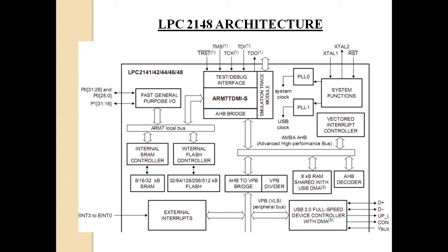Otherwise, if some sunlight is allowed to fall on that, sunlight also will have a certain amount of UV rays in it. So those UV rays may corrupt the data present inside the EPROM. In order to avoid that corruption, one sticker will be pasted. So that IC is nothing but your EPROM.